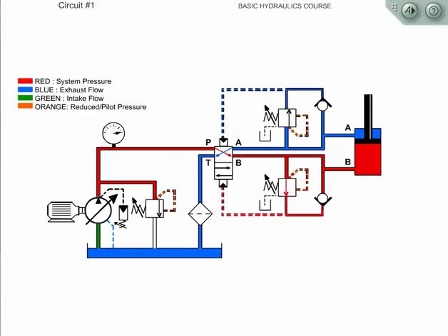Pilot pressure opens the sequence valve on the bottom. This sends pilot pressure to the lower side of the directional control valve, shifting it back into the upper position. Now, pump flow is once again directed to the rod side of the actuator to retract the cylinder, and the cycle begins once again. Tracing the flow in this circuit reveals that it is designed to keep retracting and extending automatically. Now that we understand the circuit, we may conclude that the proper function of the system will depend on the proper setting and function of the sequence valves, and the proper function of the hydraulically piloted directional control valve.